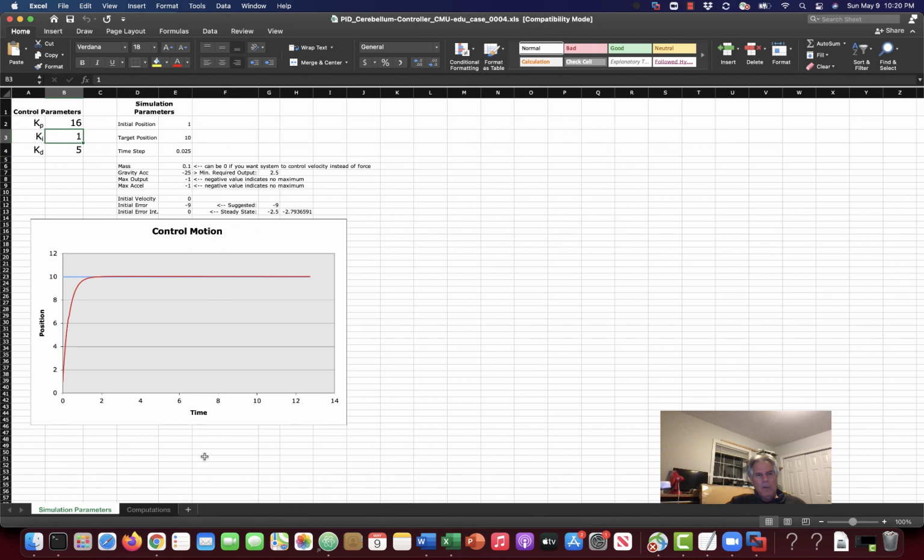And there are tuning algorithms out there, and you may even have used them in labs or whatever. But I just wanted to review the idea of a second-order control system, especially from a PID standpoint, because they're so popular. They're quite well understood. You can run them on Arduinos, you can run them on basic stamps, you can run them on all sorts of machines. They're built into PLCs, and they're a good generalized controller. And if you don't need one of these factors, you can always set it to 0.